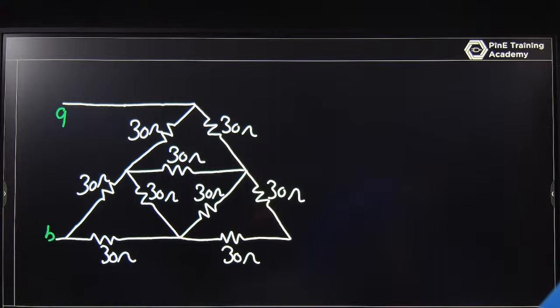Or take one circuit that we analyzed, the op amp. In an ideal op amp, we read about the ideal characteristics: input impedance is infinite and output impedance is zero. Why? Because if the input impedance is infinite, the input will be the main input for your circuit, with no internal resistance drop.